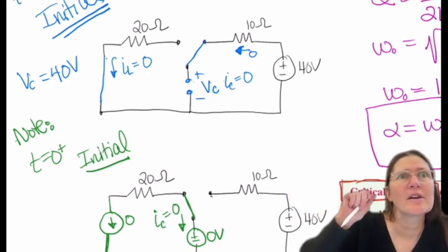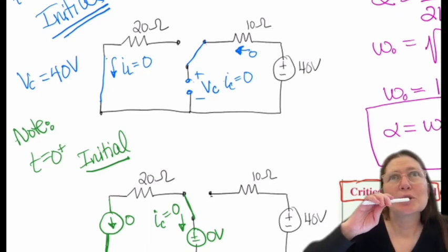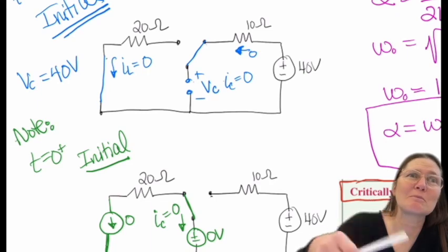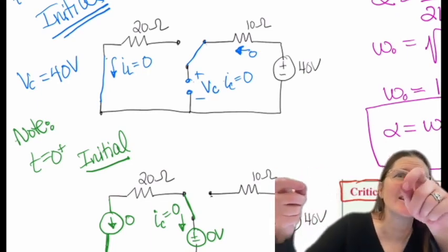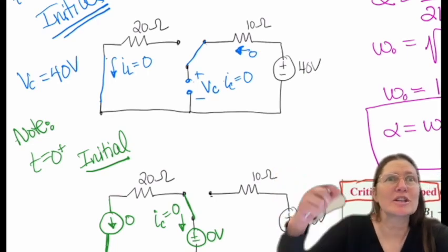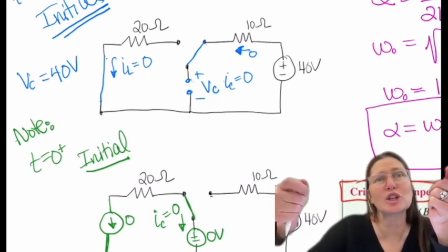Why would the inductor be a wire if there's not current flowing in it? Wouldn't it be uncharged then? If you just take an inductor and measure the voltage across it, it looks like a wire. It's the same thing when you have it in a circuit and it's sat there for a long time and not ever been charged, like you pull it out of the drawer: it will look like a wire.